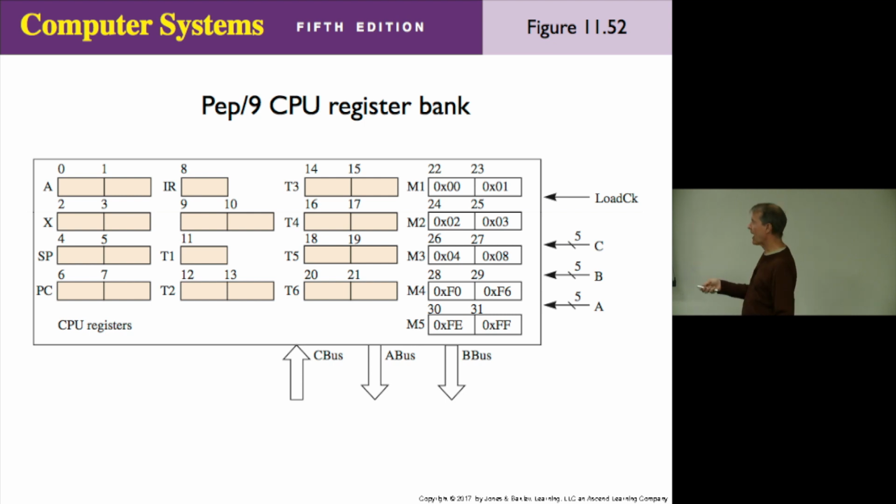Okay? This is a block diagram of the register bank. And how does it work? This is basically just a memory, just like we did our memory module. And these really are very similar to D flip-flops. This really is static RAM, because we want this to be fast. This is in the heart of the CPU. We want this to be fast.